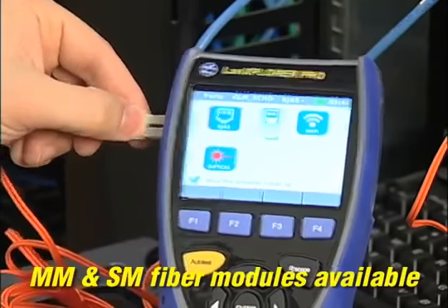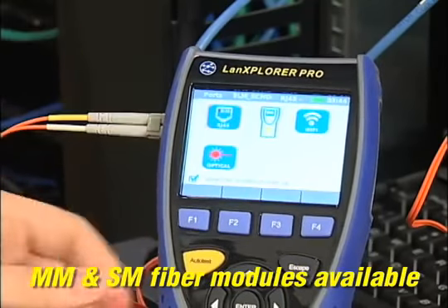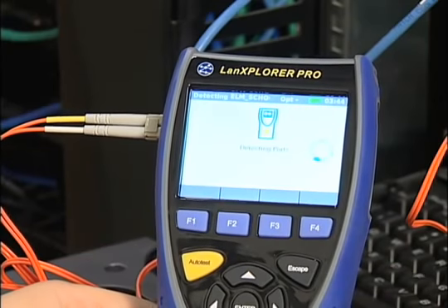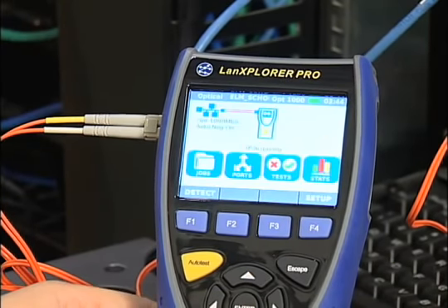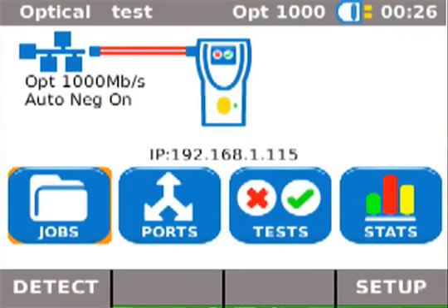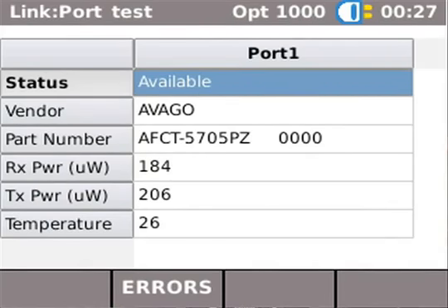Fiber optic endpoint monitoring is done by plugging a fiber optic link cable into the port on the left side of the unit. You can determine the network configuration, and the main screen will display important parameters including link speed and type, IP status, and the optical power from the switch. Again, you can select narrow or wide scan to automatically classify devices, then store the netmap to detect what's new or missing on the fiber optic network.